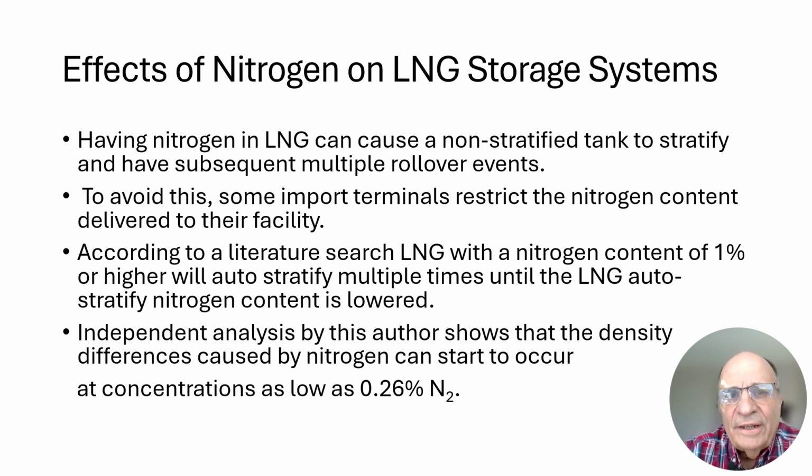If you have a high nitrogen content in your feed gas to an LNG liquefier, it is likely that you will have a high nitrogen content in your LNG. Perhaps your feed gas has 3% nitrogen in it, your LNG might have 1% nitrogen in it.